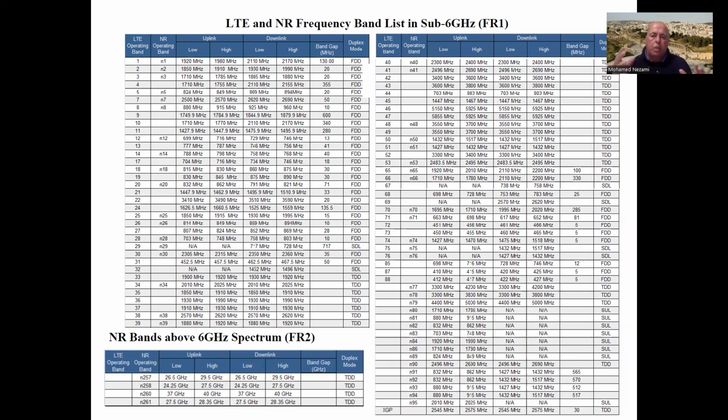So it's very much that with the 4 gigasamples per second, you can subsample most of the LTE and FR1 bands. And of course the bandwidth, there are hardly only two services that I saw with a bandwidth of more than a gigahertz. Most of the bandwidths are in the hundreds of megahertz and readily available in the ADCs. Most of these ADCs that are sampling at 4 gigasamples per second cover up to like 8 gigahertz 3 dB bandwidth. So they are appropriate for the FR1.